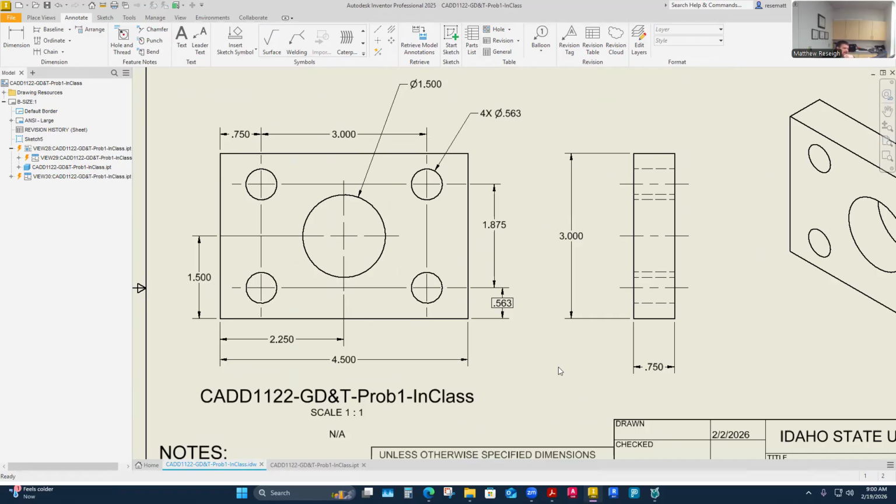It's theoretically exact. It's how we draft and draw in solid model generally, using those theoretically exact dimensions. But that's a higher standard than we can hold manufacturing to. So they created this system that's like, okay, now let's deal with reality, that things are not made perfect. And actually they just cannot be made perfect. So we have to develop a way to say what's acceptable and what will still work and still do its function and be interchangeable. They call it interchangeability in our chapter a lot. I think of it as functionality more. It'll function as it's designed.